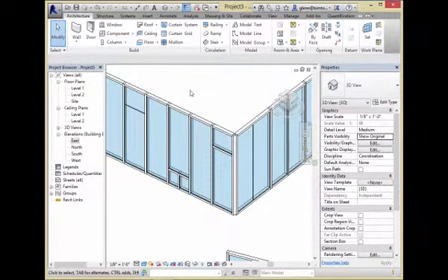Now, I've been taking out the mullions. Turns out the grid is still there, so we might have to get rid of the grid also, because the mullion and the grid line are really two separate things as far as it's concerned. And how do you get rid of a grid? It looks like this. You come on over here, you choose the grid. Let me warn you about this. This is where your tab key is going to come in handy.